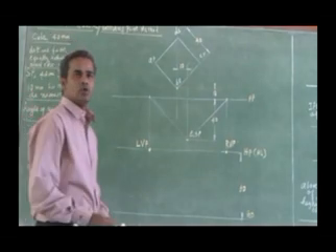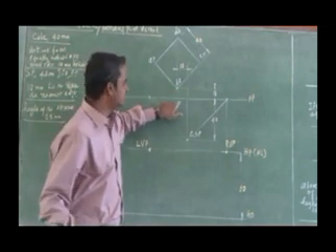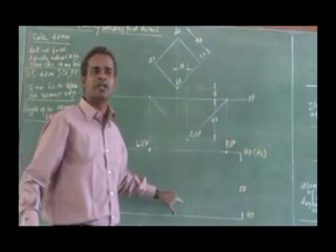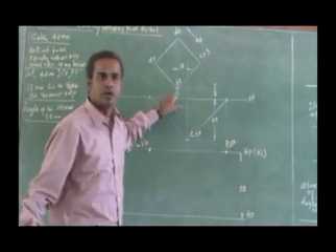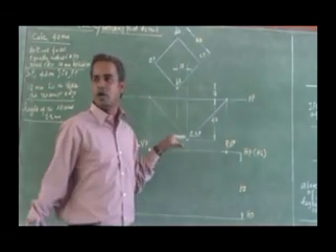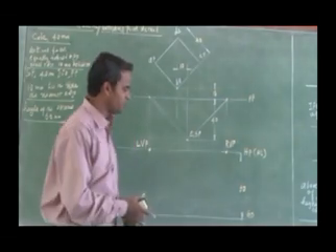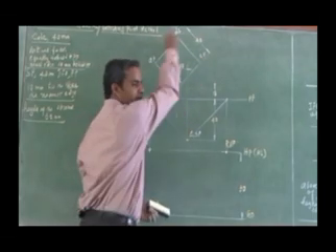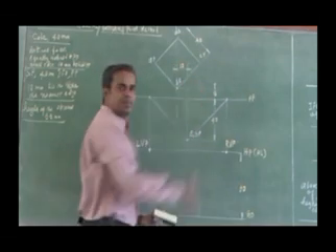You know one thing. Listen, all of you. If my edge is touching the picture plane, the same length will be obtained in my perspective. Do you agree with that? That is the concept I am going to use. So the true height of the cube, I am going to draw from the picture ground plane. From this location, I don't find the true height for the vertical edges, because all the vertical edges are behind the picture plane.